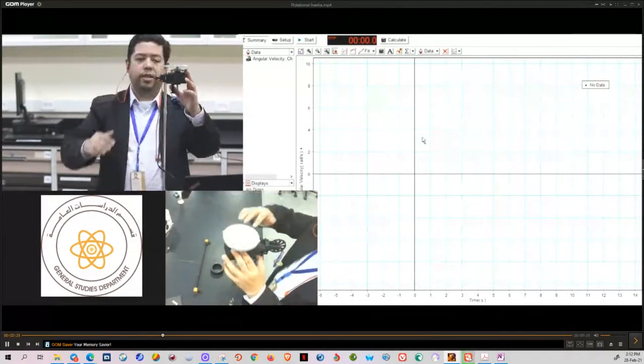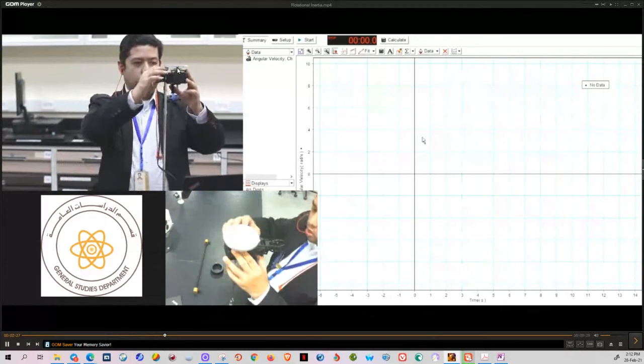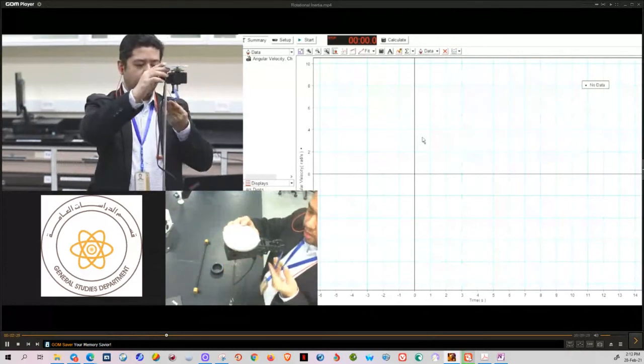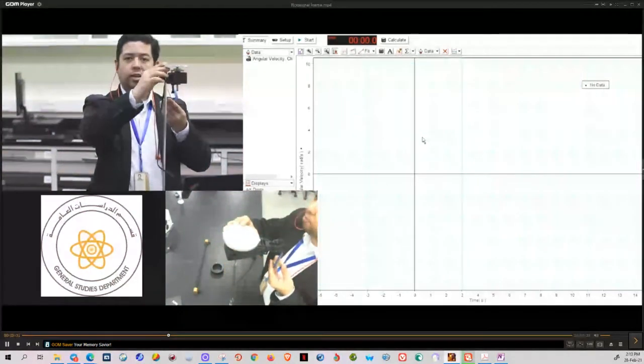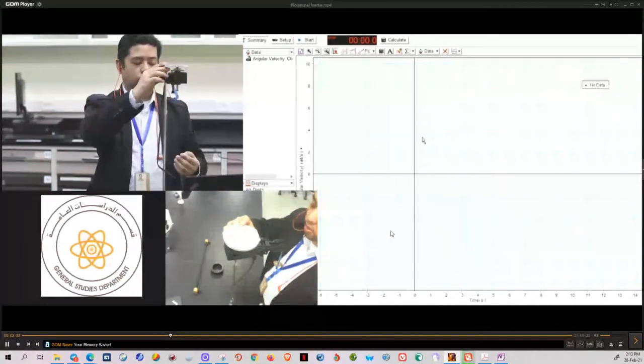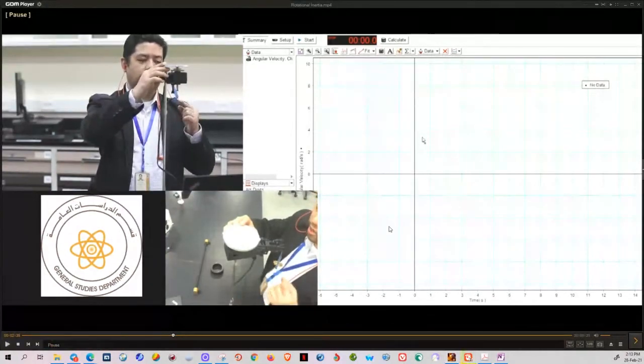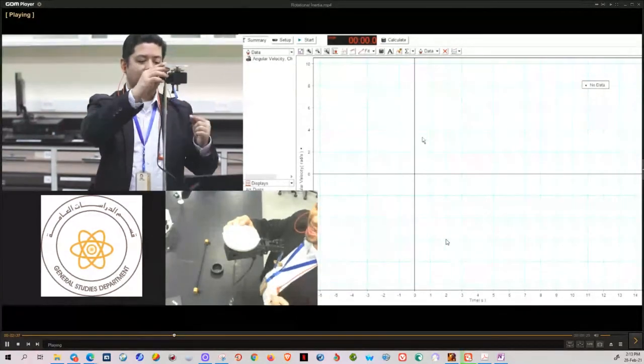Okay. So you can see the string. The string goes around the pulley. Make sure that the mass, which is going to apply the torque with gravity, is not swinging. Okay, that's important. This mass should not be moving like this. It should not be swinging. If the applied mass is swinging, it's a source of error. What's the precaution? The applied mass should not be moving. It has to be steady.